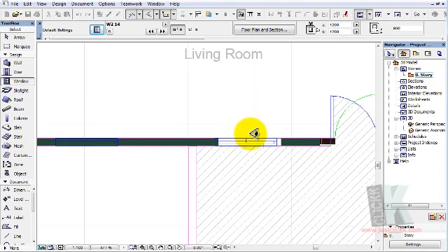Now this is not a door, so we're not going to talk about the opening angle or whatever. This is a sliding window. What you need to observe here is the recess. How do you want ArchiCAD to recess the windows? Should the recess bevel be inside or outside? Of course, it should be inside. So you take your cursor inside and then click. This is how you fix the window.